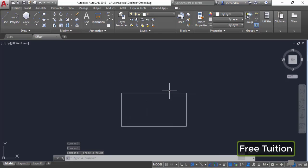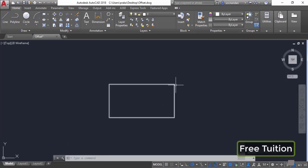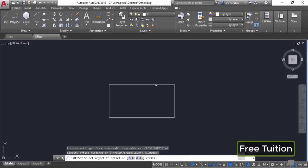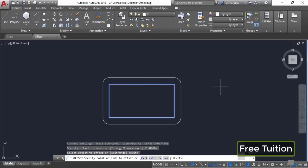And now let's look at some other options related to the offset tool. Here the offset is making similar geometry to the one we have made here, but if you want to apply rounded corners on the offset geometry, you can do that by changing the OFFSETGAPTYPE system variable. So let's type OFFSETGAPTYPE and press enter, and here you'll notice that the default value of this variable is set to 0. Let's change this value to 1 and press enter. Now we'll again make the offset. Select the offset tool, specify offset distance as 1, press enter, click on the object, and now click outside, and now we have a different geometry here.